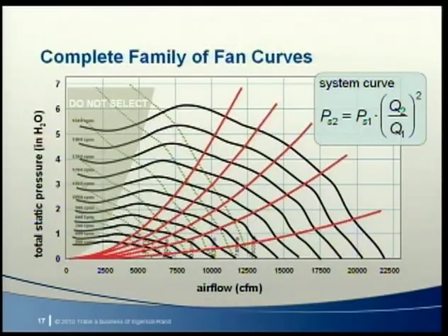This reverse flow can cause a noticeable fluctuation in both airflow and fan static pressure. All fans surge at some airflow, so to avoid it, a minimum airflow limit is established at every speed for every fan. This limit defines the do not select area to help designers select fans that won't surge. The surge limit depends on the fan type, and it can vary widely.